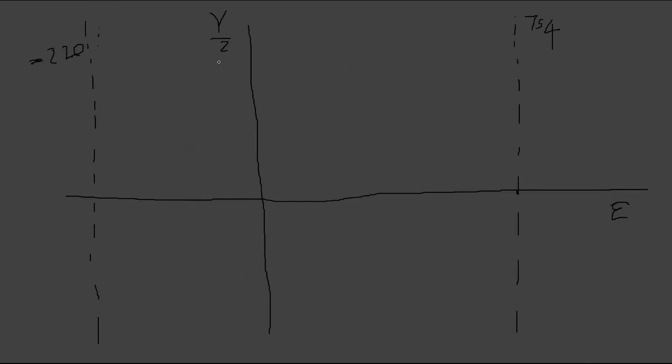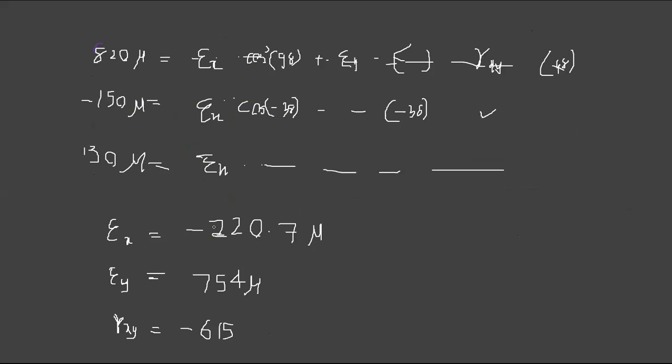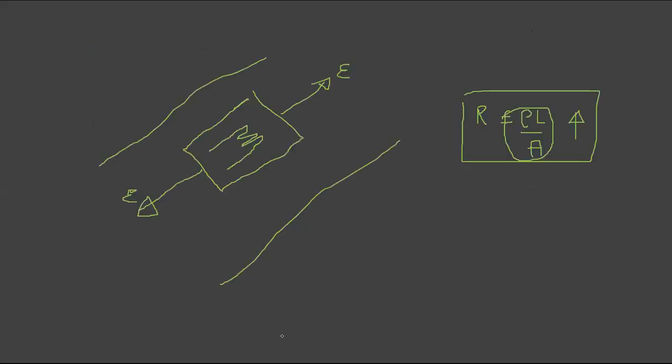So before that we have an important step. Actually we are not robots, right? So sometimes we are being taught, okay, if your principal stress is this, take the direction of shear stress at that, right? So we actually do not need that, right? We can take it from the first principles, because just have a look at these strain values. Epsilon x is negative, epsilon y is positive, and gamma xy is negative, right? Just keep in mind, it's like 200, 700 and 600 something, right?